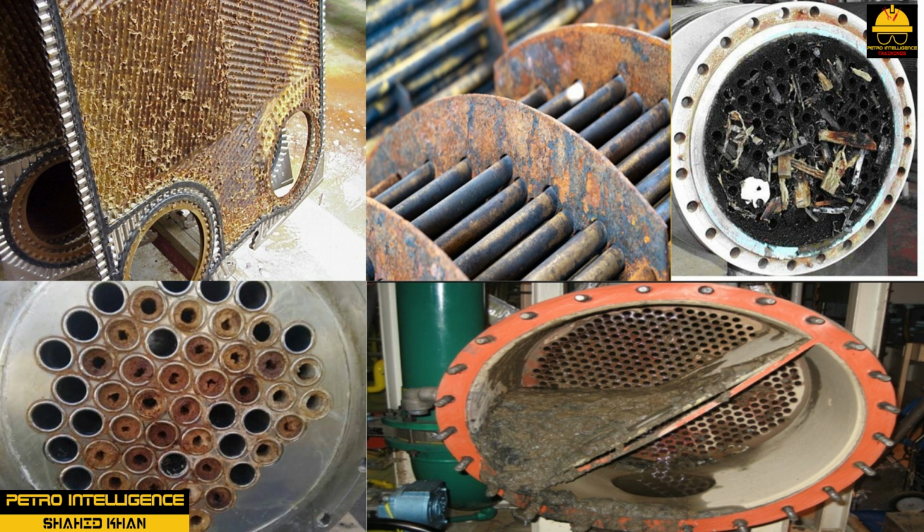Corrosion and erosion are other problems found in exchangers. Chemical products, heat, fluid flow, and time tend to wear down the inner components of an exchanger. Chemical inhibitors are added to avoid corrosion and fouling. These inhibitors are designed to minimize corrosion, algae growth, and mineral deposits.